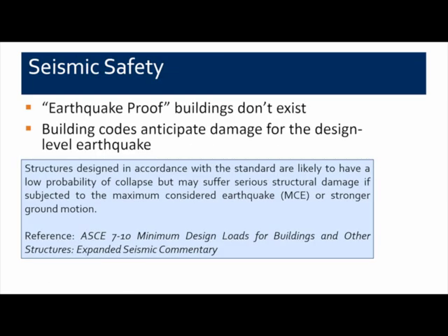But first, let's talk about a common misconception. Earthquake-proof buildings don't exist, despite what you might see or read in the media. Instead, what we have is an expectation by engineers, represented in the building code, that damage will occur when buildings experience a design-level earthquake.